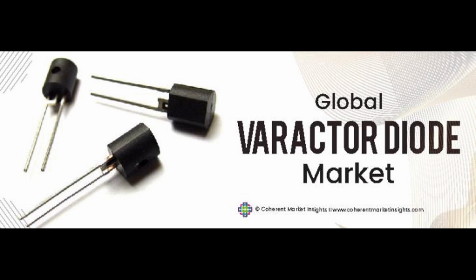4. Quadrature modulation circuits. Quadrature modulation techniques, such as quadrature amplitude modulation, QAM, and quadrature phase shift keying, QPSK, combine both amplitude and phase modulation. Quadrature modulation circuits include QAM and QPSK modulators. These circuits generate signals with combinations of amplitude and phase variations, allowing higher data rates and more efficient use of bandwidth.